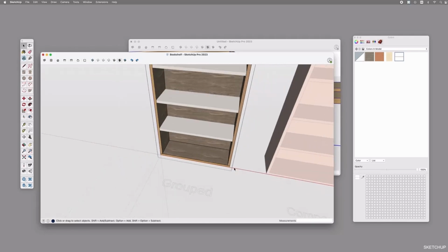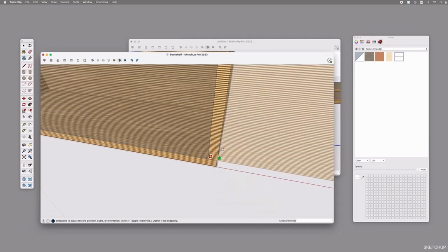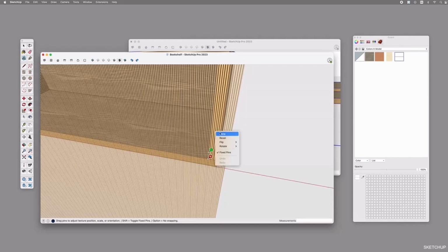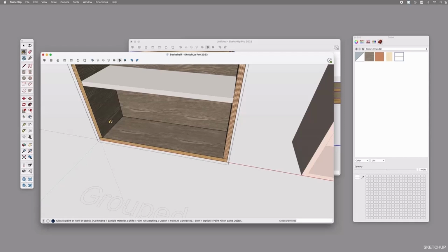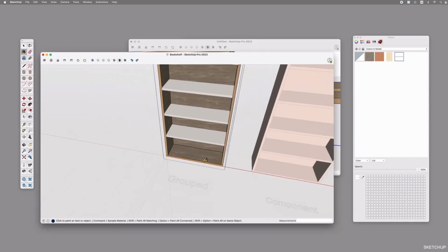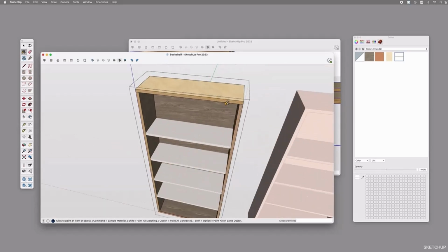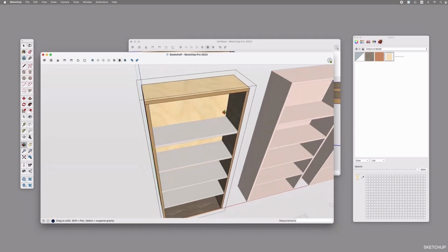And then we can rotate the texture vertically on one of the sides. We will then sample that modified texture, and apply it to the other side. This method illustrates how to obtain a texture from the warehouse and apply it to your 3D models by sampling a material from any object.